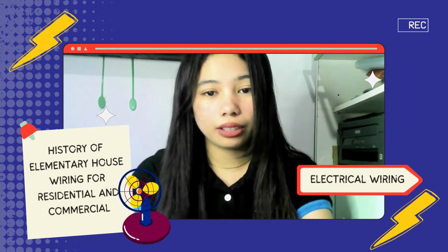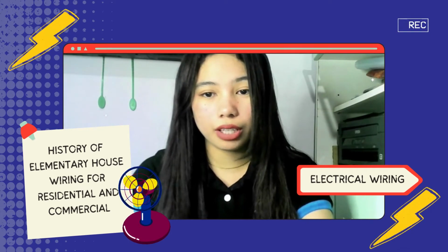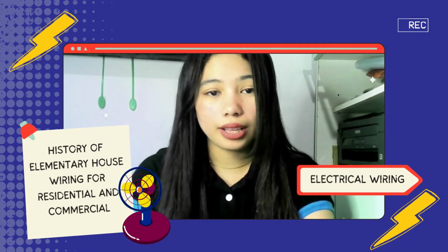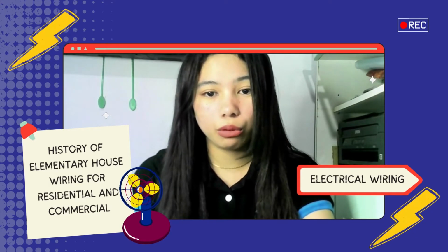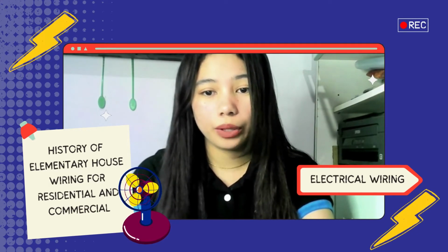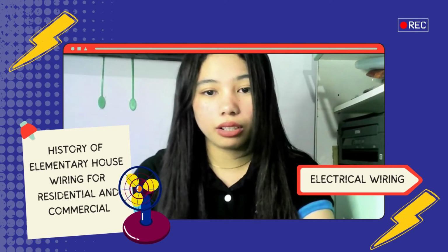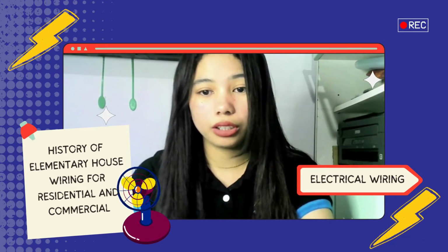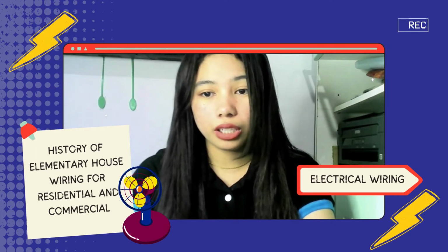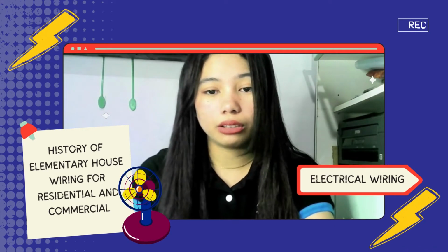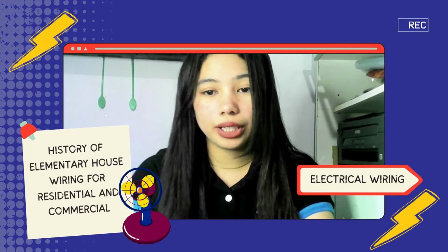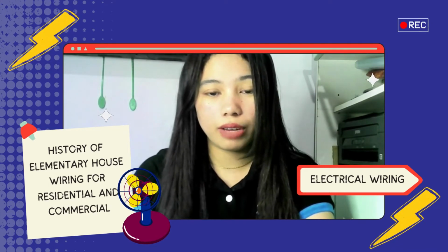From 1880 to 1940, knob and tube wiring was the first type of electrical wiring in homes. This type of wiring consisted of two single wires run parallel within wall or ceiling cavities. The wires were run through joists and stud holes through porcelain tubes and supported along their length with porcelain knob insulators, which were nailed down. Knob and tube wiring was labor-intensive and expensive to install, eventually replaced